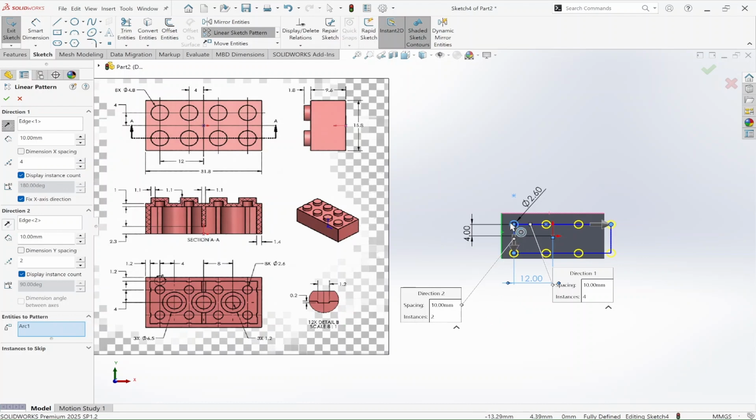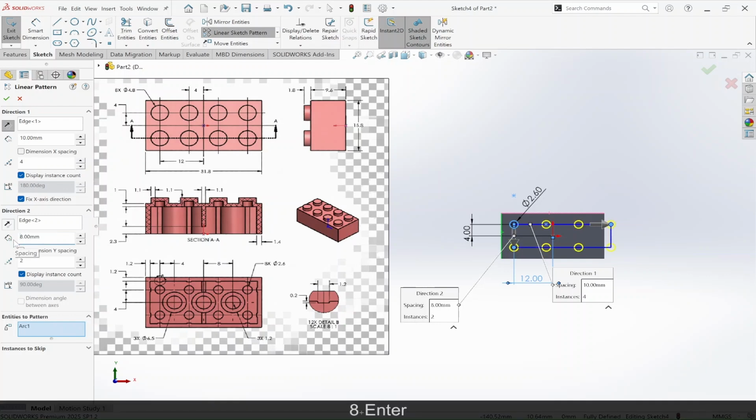So I have to define the gaps between each entity. For that, you can again observe your drawing to get the gap between them. So as you can see, my object is a symmetrical object, and from the central axis to the center of this central block is 4 mm. So the distance between two connector blocks in the vertical direction is 8 mm. So along the vertical direction, I will define my spaces of 8 mm.